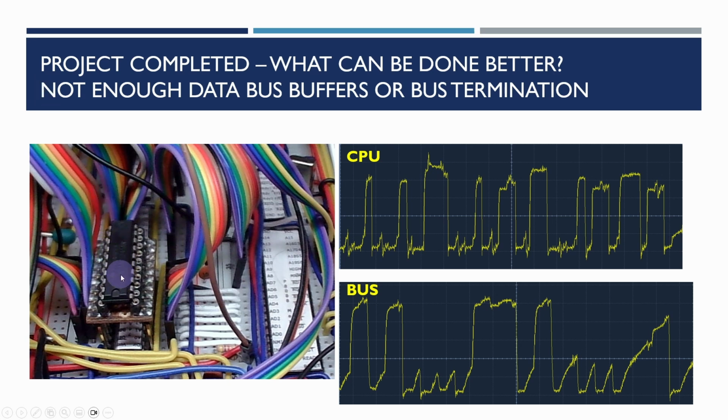Now the other bit that at the time I remember talking about in a video is that theoretically the ALS chips that I was using had a fan out of about 40, so an output from one of these chips should be able to feed about 40 inputs. However, I did find as I was doing the DMA controller that I actually piggybacked another buffer on top of the base buffer here to give it a bit more oomph, because I thought that might have been one of the problems.